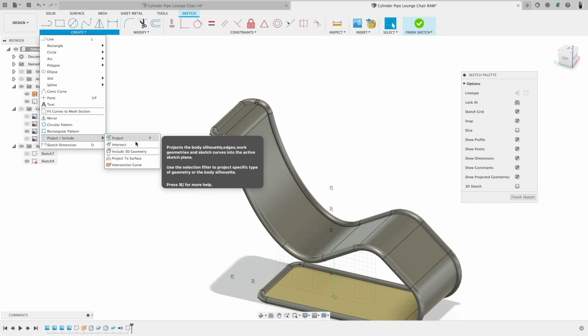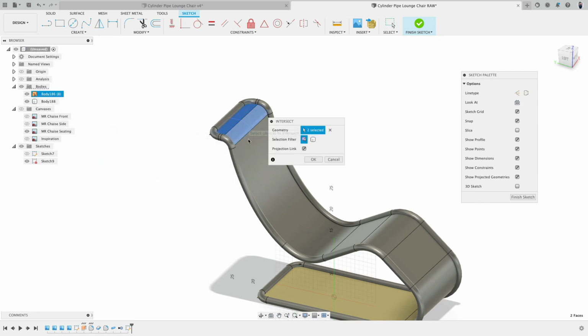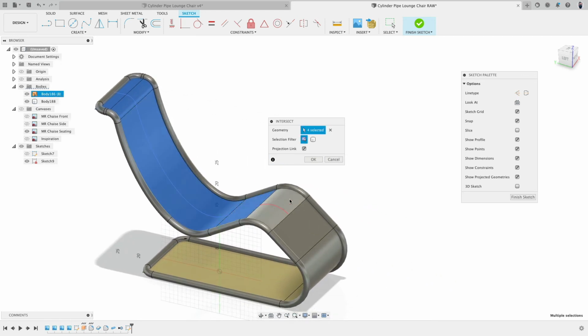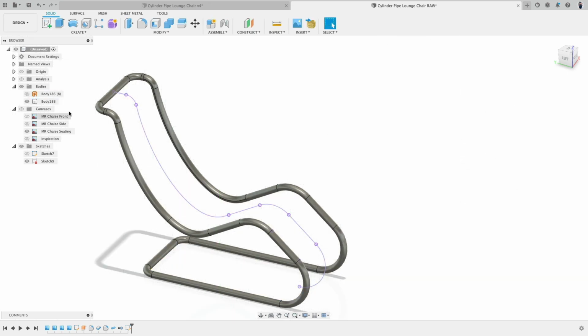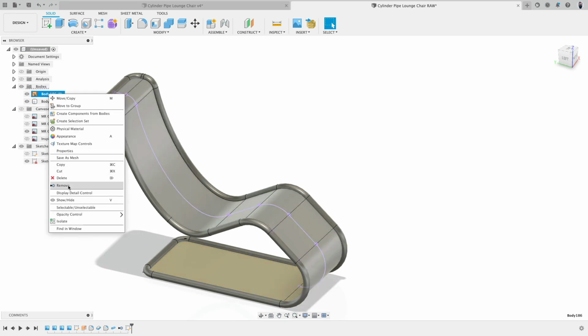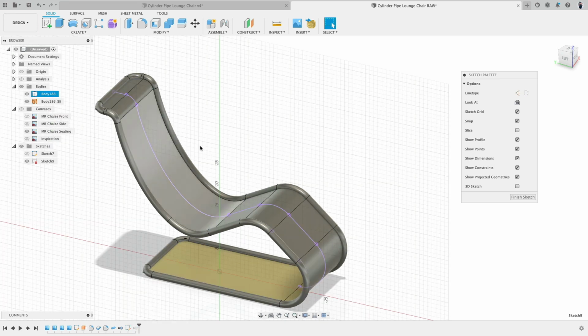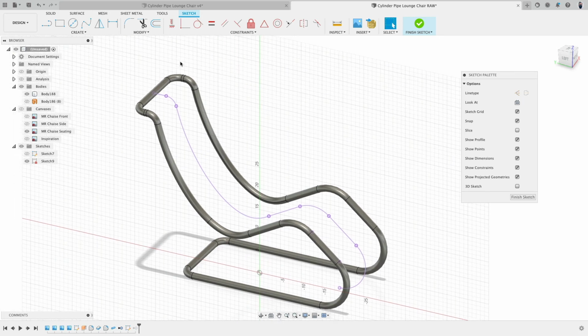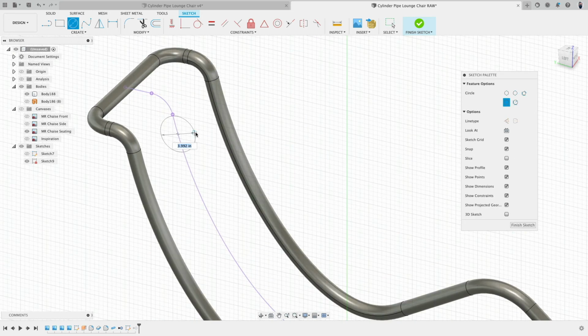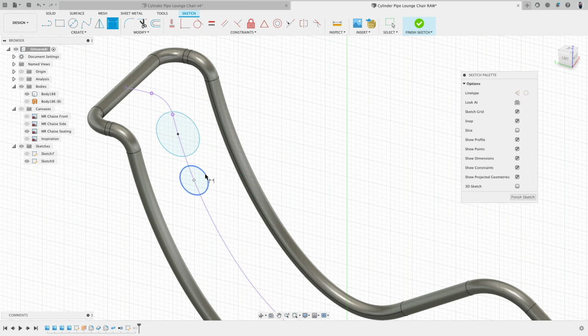We go to project intersect, and then I simply intersect these lines or surfaces, and that generates then the sketch for me. There you are. You see? Pretty simple. Now this surface I can remove and then go back to the edit sketch. You see the surface is back because I jumped actually back to the sketch and it's in front of this delete command. So in case you get confused. And now I can continue or repeat what we did before.